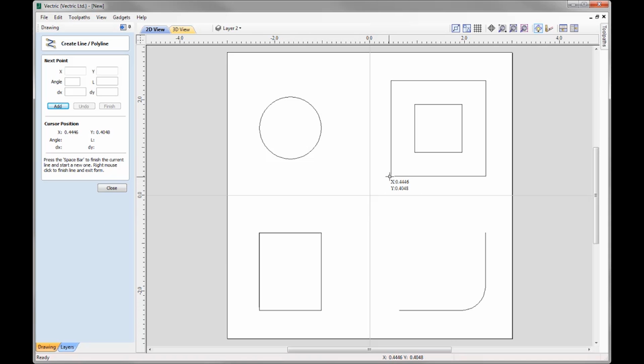simply come over, wake this point up here, wake this point up here. Then as I come back, you'll see I'm now displayed an olive green line, and you'll see my cursor's change. It's telling us that we have now found a connecting line. If I follow that along, you'll see I now have a snap point. That's telling me that this is the dead center of the two points that you just woke up. And I can click that to begin creating my shape.